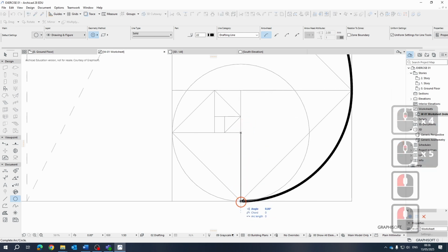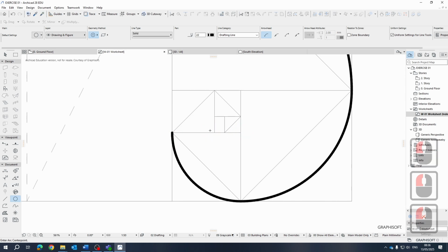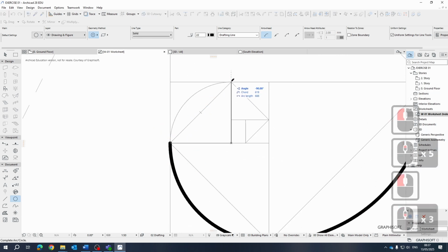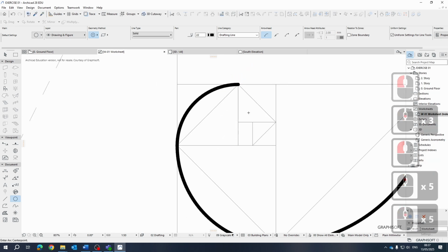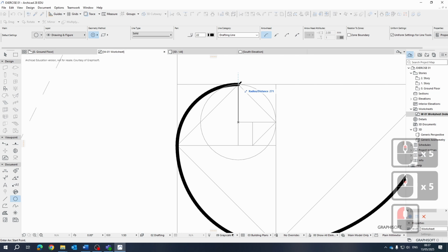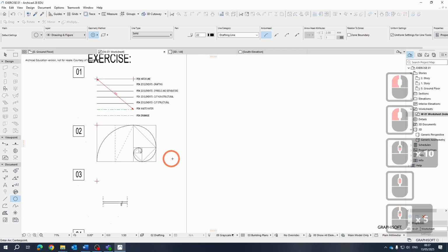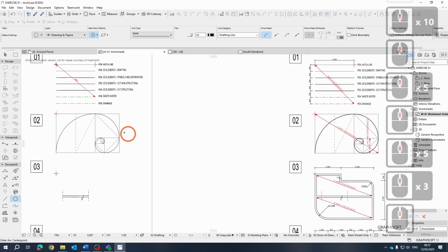Okay, so this is quite interesting. You want to work with geometry or line work that is mathematically sound. When you start using splines or objects that require a lot of maths to set them out and reproduce them for a contractor, it gets very difficult. So if you're going to create curves, try and adopt a mathematical principle that a contractor can use to set out your design on site. Just remember, a lot of these curves do come with some complexity, which makes them very difficult for somebody to reproduce. Okay, so that was straightforward. You can see it was very easy to create this shape.